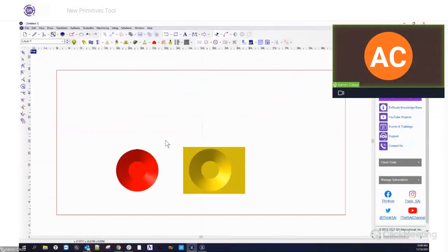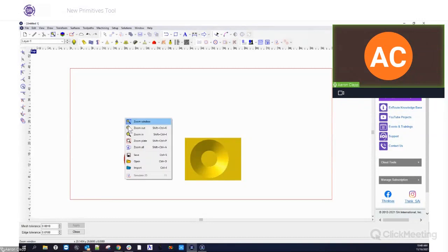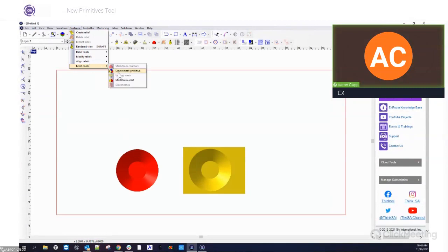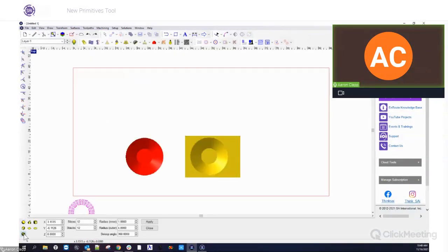So that's going to be creating those shapes. And again, you can come in here and check out some of the, oh, I clicked the wrong thing. Mesh tools. We've got a shape here for, I guess this is like a torus shape, like a donut shape. And so you've got your inner radius, your outer radius, and then a sweep angle. You can do a complete 360, or for example, if we do a 180, do half. That's kind of a half donut shape there, or half arc shape.